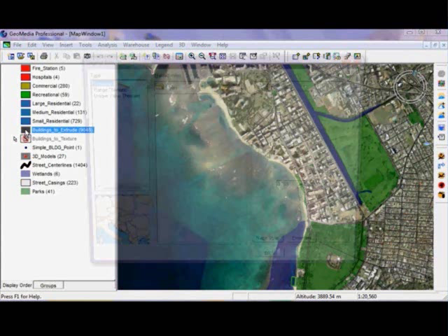So what I've done with the residential, because I have some more definitive detail, I've done some GeoMedia queries, and I've broken it up into small, medium, and large based on the number of floors that I have in that building. So, you know, obviously the high rises, anything above 10 floors or so will be large. Anything between 3 and 10 will be a medium, and less than that would be a small. And I did that for the purpose if I wanted to assign different textures to them, I could. And I didn't actually do that here, but just wanted to give you a flavor for that.